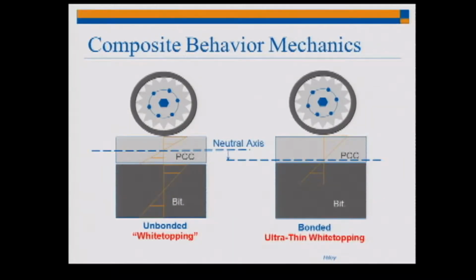So one thing we like with the bonded system, at least for asphalt, concrete can be placed on probably a more deteriorated asphalt pavement than if it's a deteriorated concrete pavement. You really don't want to put concrete on concrete.